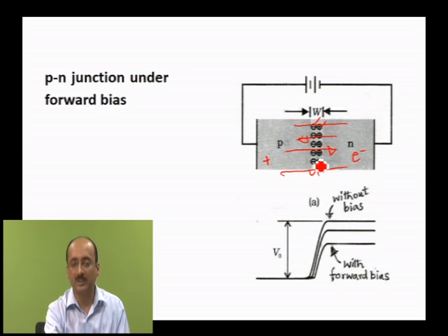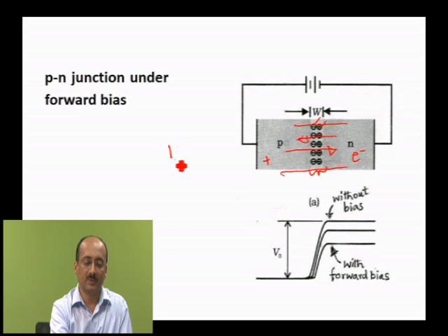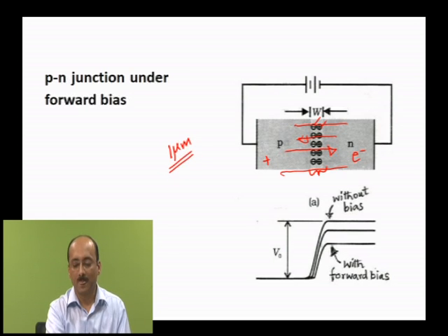So for the depletion region to be developed, majority charge carrier diffusion is the process, and usually this depletion region width will be a micrometer thick, and biasing etc. will be done. Biasing generally means you are connecting a source of EMF across the PN junction. When you do so, depending on how you make the connection, either the depletion region width decreases or it will increase.